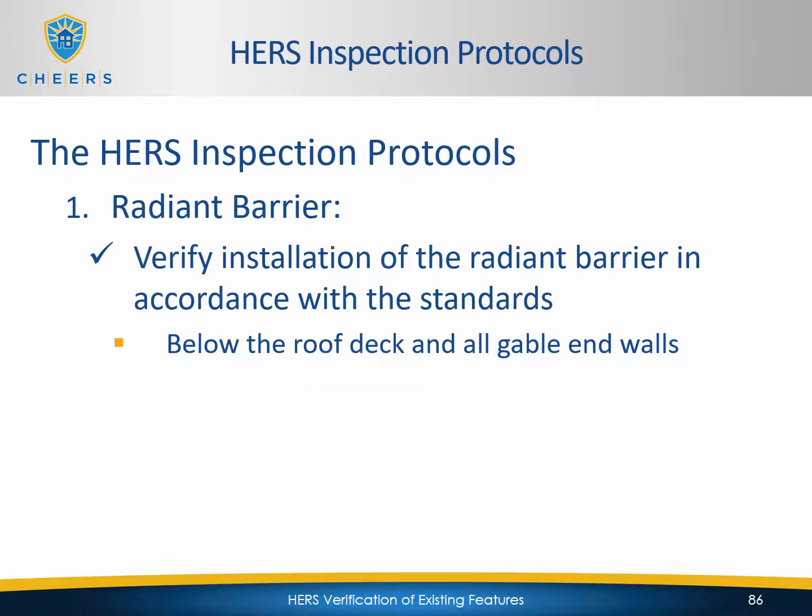For radiant barrier, you just want to verify that the installation is in accordance with the standards, which is below the roof deck, and all gable end walls also have to be wrapped in radiant barrier, just like we talked about in the Title 24 overview.